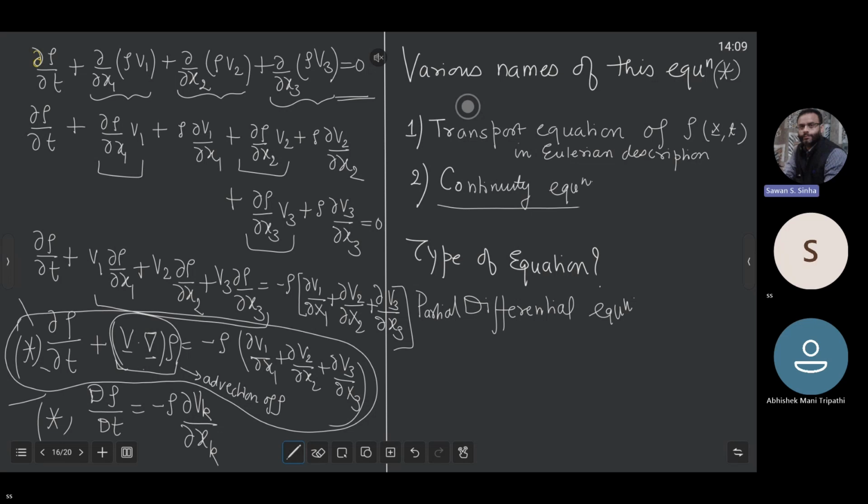Right? If you know somehow the background velocity field, V1, V2, V3 everywhere, then you can think of solving this equation. For what? We'll solve this equation for density if V1, V2, V3 are known. All right. Actually, sometimes this is also just called the rho equation. So if V1, V2, V3 are known, we can think of solving this equation.